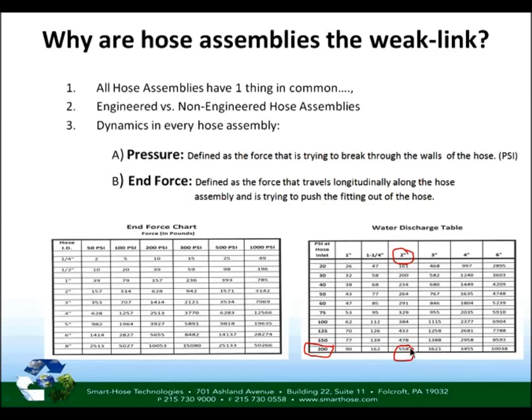Now that's just for water. LPG has an expansion rate of 270 to 1. So multiply your 558 times your 2 ends: your hose blew off, and your plant pipes. You have 2 ends that are released, and then multiply by the expansion rate. This is the reason why a passive safety system is so important. The hose reacts to the catastrophic failure and shuts off the flow immediately. And the beauty of the smart hose system is the simplicity of it.